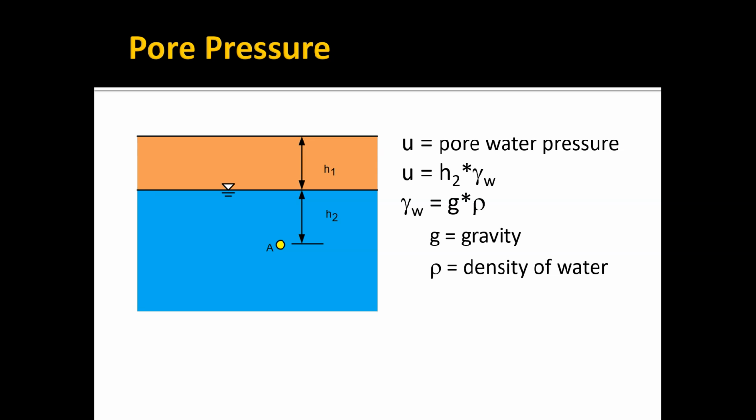The line there, this little symbol right here, is an indicator we typically use to represent what we call the water table. That is, if you were to drill a hole in the ground, it's the level to which water would rise in a pipe. It's the top of the saturation.